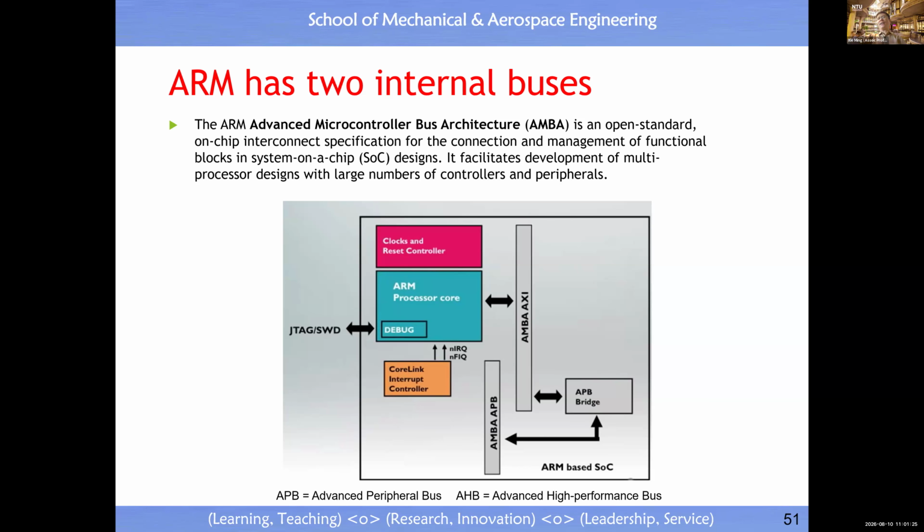So we have two address buses going to the same memory location. That means we can achieve a higher volume of data flow. But this knowledge is very important for you to understand when you study the second part of this course. For each register, we have two addresses. Why? You may ask, how come I have two addresses? Answer is, because we have two highways, two address buses.